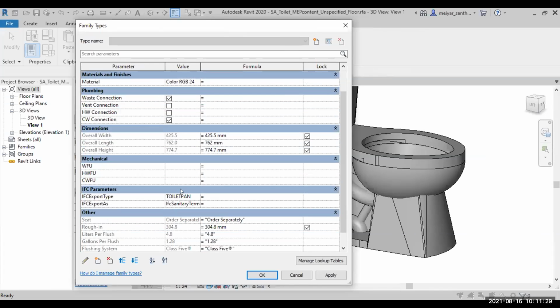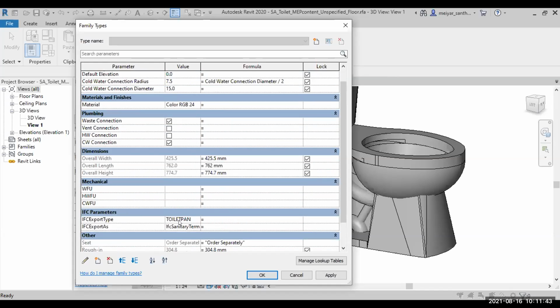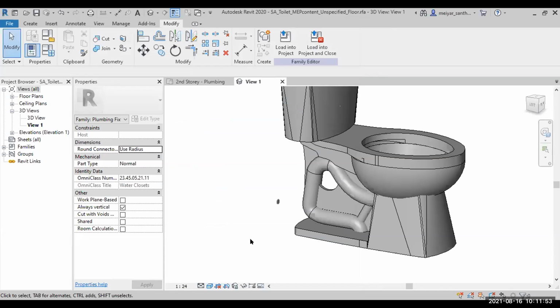This is for IFC information when you export out for sharing. Then the rest is like the seed, or the formula. This one is some calculation conversion. So in imperial, look at it, because it is per gallon. Okay, so more or less if it's done, apply. Now, this is a connecting pipe which you can ignore, but when you insert at time, you can base on your drawn pipe, take this as a snapping point, so it comes out.